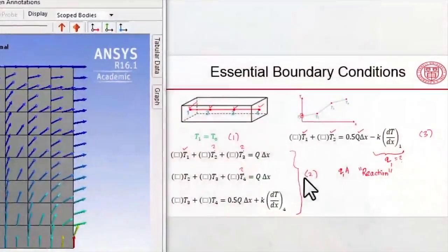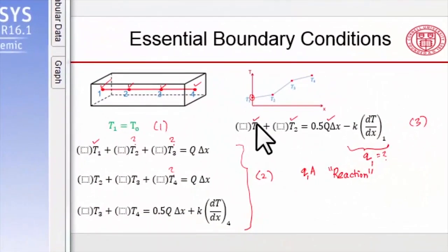And you can save the project. Let's check the energy balance. In the big ideas in FEA, we saw that from the discrete equation, at the essential boundary condition, we were able to calculate the reaction, and that involved the heat flux at that node times the area of that face. And that was step 3 in the finite element procedure. And so that's what we will do.